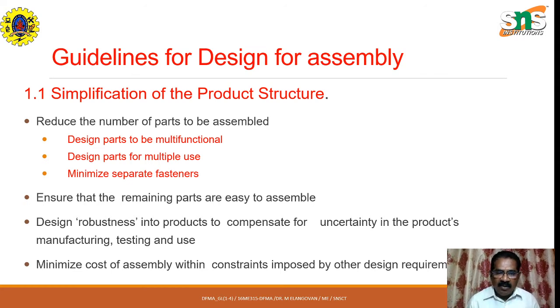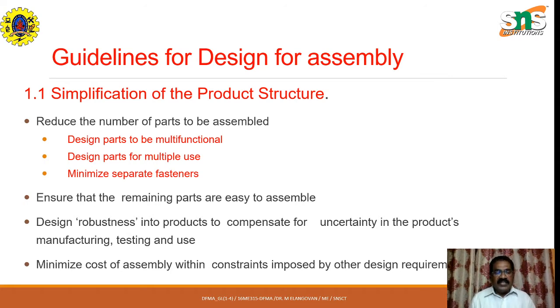They may break. But what happens here is that they have just done a snap fit, so that the back cover just opens out beyond a certain force from inside, and then you are able to assemble it back inside properly. So, design robustness into the products to compensate for uncertainty in the product's manufacturing, testing, and use.